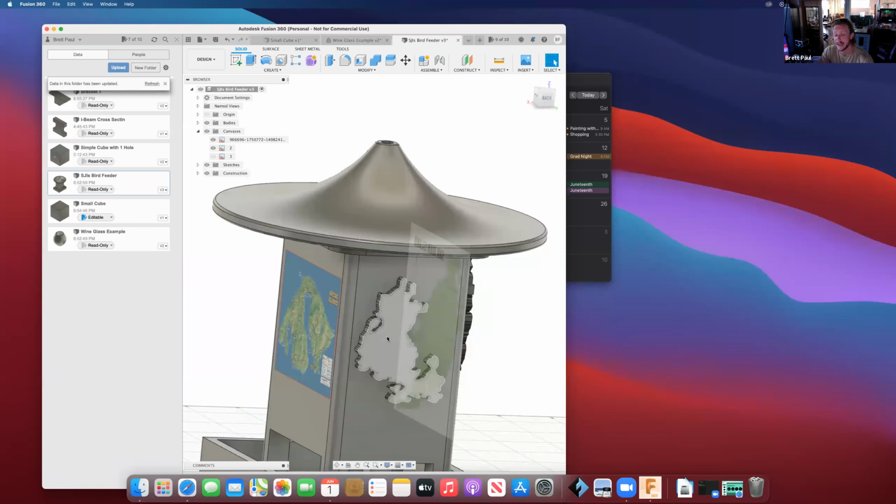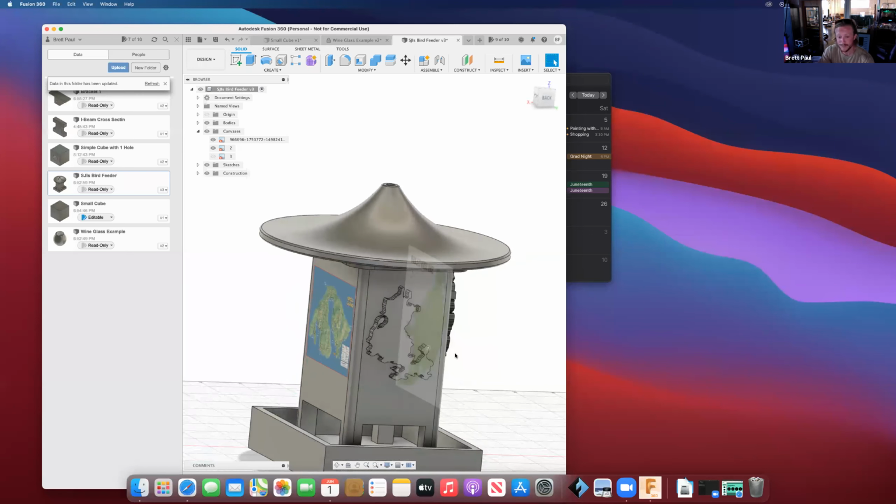Now, there are many other ways to approach this. You could, for example, 3D print each wall separately so that your islands are printed directly onto the wall face, and you don't have to glue it. So this is just how I'm going to do it. I might change it as I look at it closer, but that just gives you an idea of how to start thinking about how we design in CAD, and then how we take that next step to making the part designed for 3D printing.